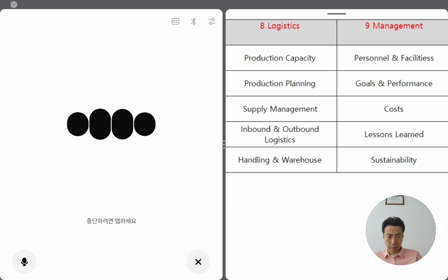1. Arrival. Parts come sealed with desiccant plus humidity card. 2. Storage. Put in dry cabinet or nitrogen cabinet. 3. Use. Track the floor life timer once the bag is opened. 4. If expired, bake before using again. That's it. If you just remember this sequence, arrival, storage, use, bake, you don't need operator level detail. It's enough for you as a quality manager to explain confidently in front of an auditor or customer.